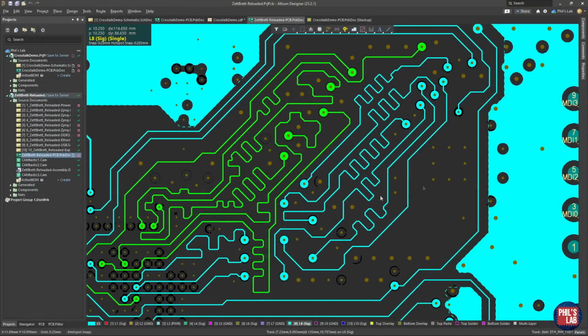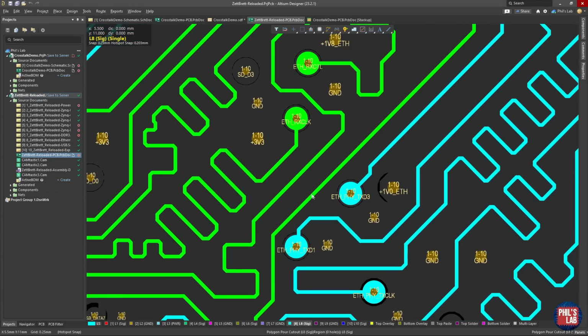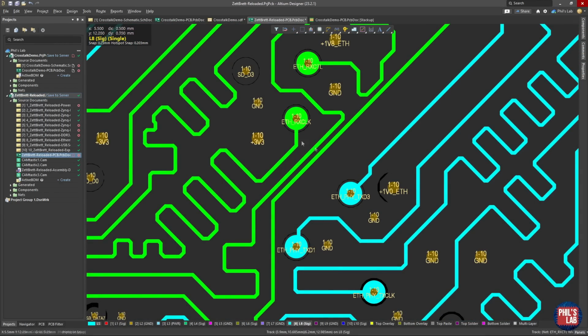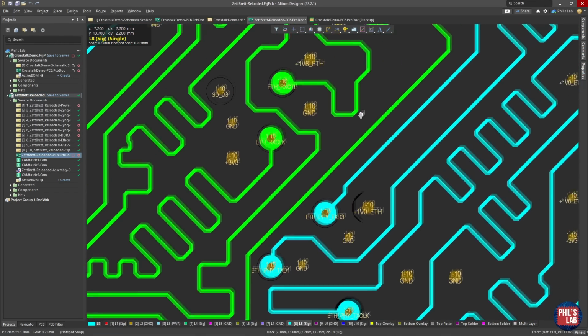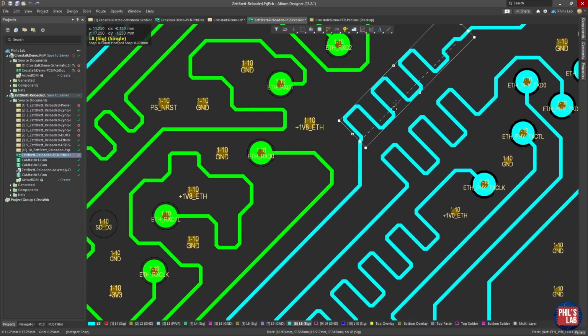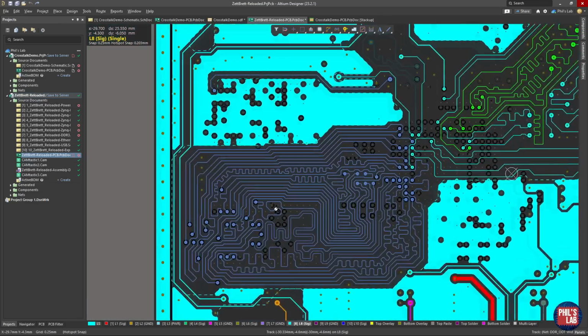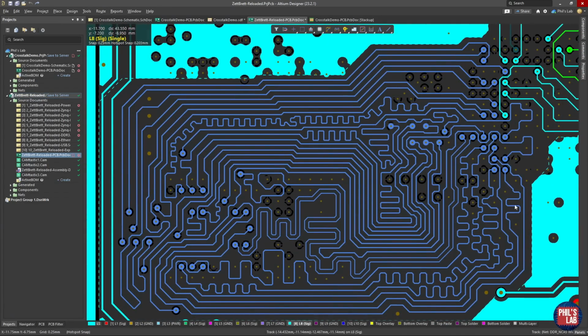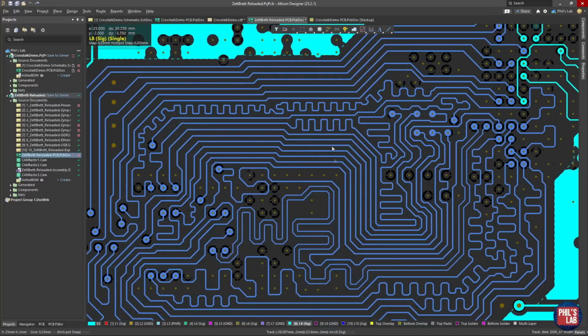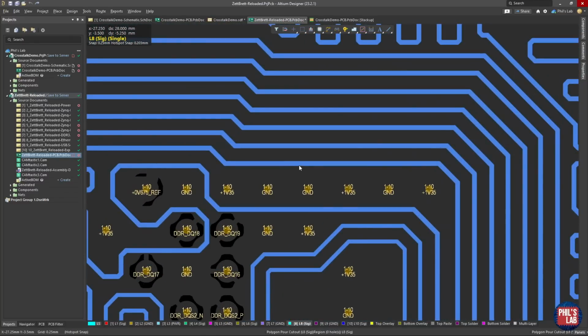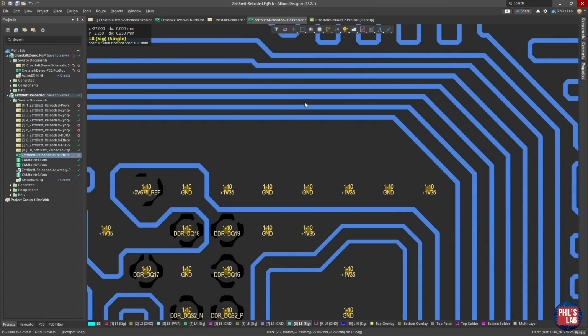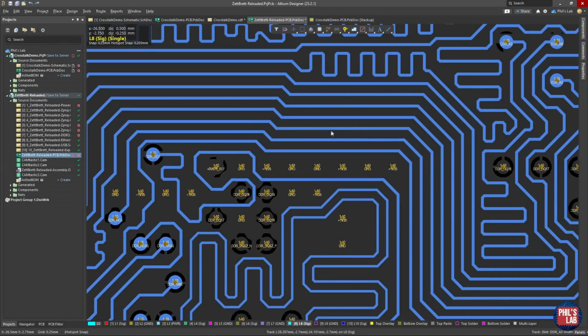For example, in this PCB, these traces are part of a gigabit Ethernet interface between a MAC and a PHY, and you can see any place I can, I'll try and space out my traces. And this is not just the traces themselves, so I could have them of course close as this, but this would increase the crosstalk, so I space them out as much as I can. But also these delay matching meanders, I want to space them out as well, because of course we can have intertrace crosstalk. In some cases, for example, this DDR memory bus, we have a lot of parallel traces that are forced to run very close together, but we still want to do as much as we can so we don't squeeze them together like so, but we maximize our space between them, again, for crosstalk reasons.